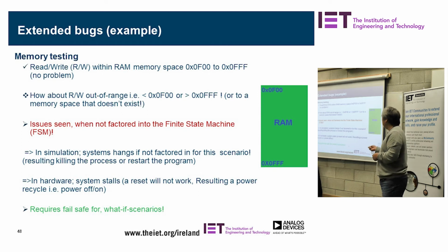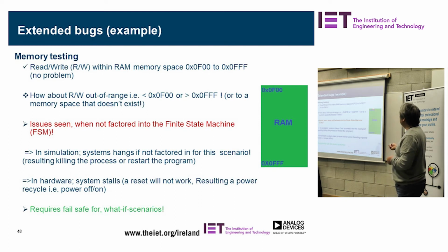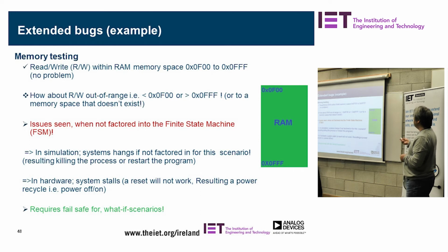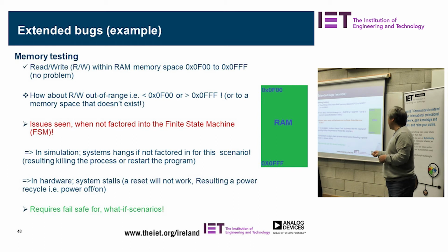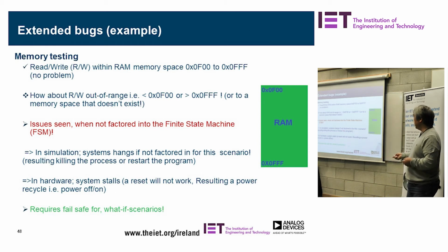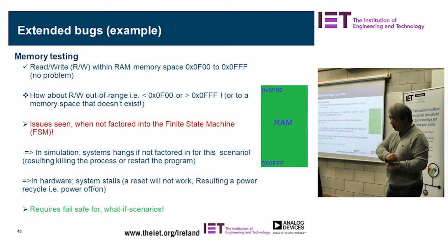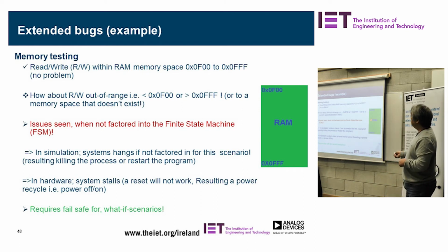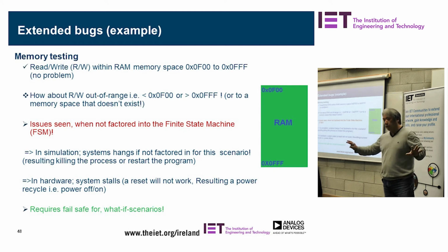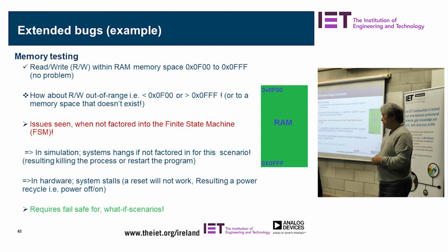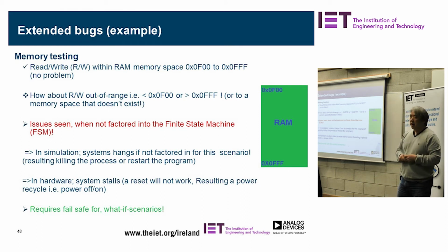Okay. So imagine you have memory you want to access. You can read and write it, okay, but what happens if you read outside this memory? The whole thing collapses, and in simulation it hangs. You need to kill the process, and in hardware, if you come across a system that stalls, even if you press reset it will not reset, you need to power it up and down in order to reset it. So when you see a situation like this, it's extended, but they haven't accounted for testability outside the area.